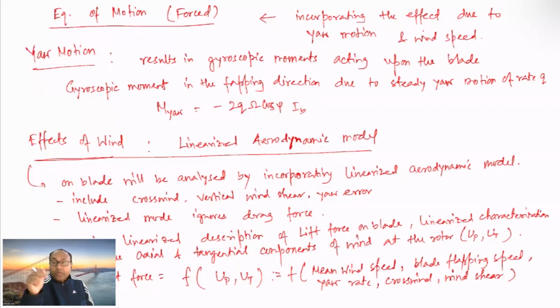Welcome back. So we'll continue the discussion on this equation of the flapping blade motion under force condition. So here we are considering the yaw effect and the wind effect, where we are going to look at the linearized lift force. And linearized lift force we are going to consider because it's a simplified system. Essentially, we would be ignoring the drag force, assuming that doesn't have too much of impact on the system.